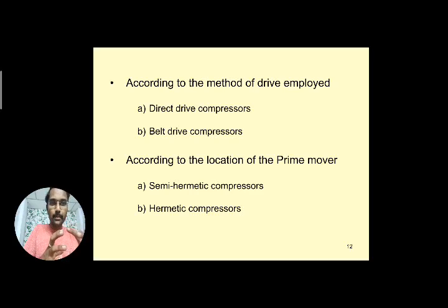Hermetic compressors are a very compact one. So depending on the location of the electric motor, or where we are placing it, depending on that condition we have open type compressors, semi hermetic compressors, and hermetic compressors. Hermetic in the sense is a completely sealed compressor.